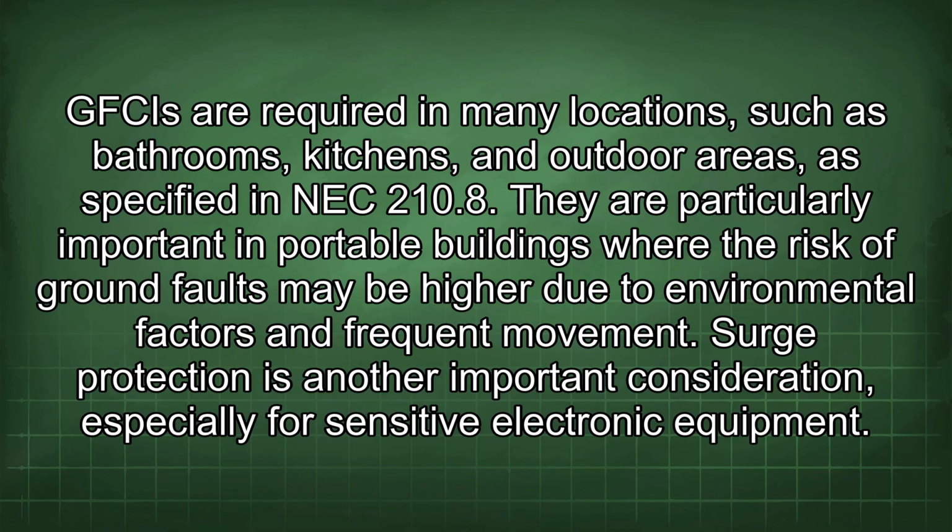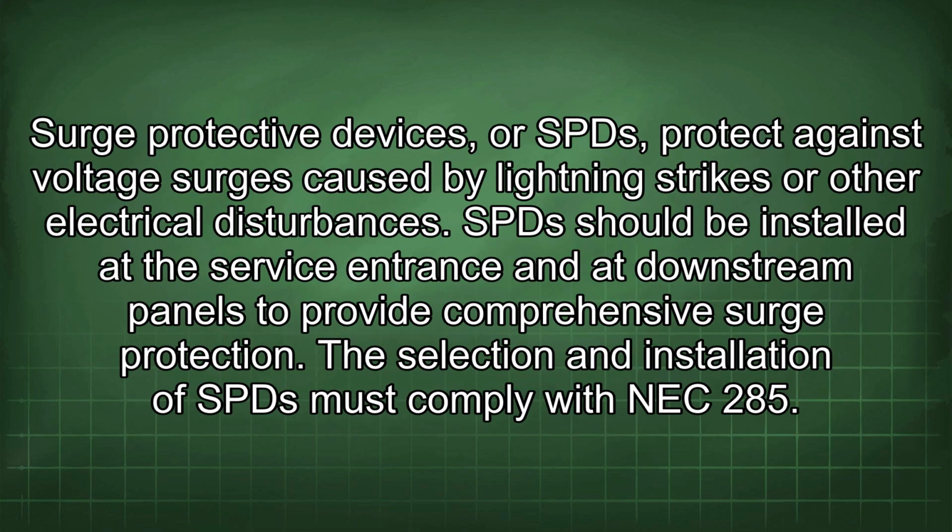They are particularly important in portable buildings where the risk of ground faults may be high due to environmental factors and frequent movement. Surge protection is another important consideration, especially for sensitive electronic equipment. Surge protective devices, or SPDs, protect against voltage surges caused by lightning strikes or other electrical disturbances. SPDs should be installed at the service entrance and at downstream panels to provide comprehensive surge protection.